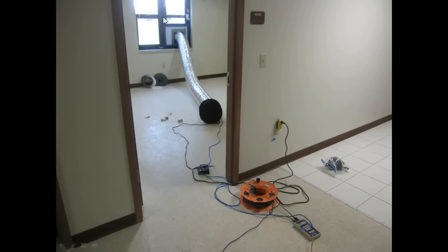Put some weather stripping around the edges and customize it for a window size. And if each apartment has the same window size and the fan is attached directly to that, it's pretty easy to move from one unit to another with that system. Or if you do set up in a door with a blower door frame and a panel with the hole in it sized for a duct blaster, again, you can pretty easily move that.